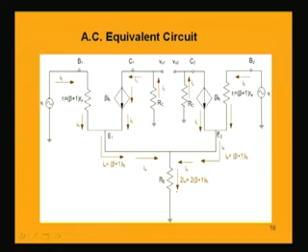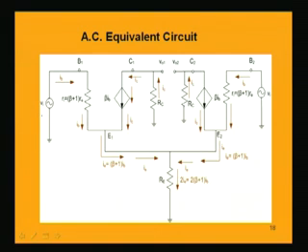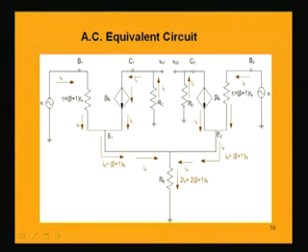Now, what will happen is that you are applying the same voltage to both the transistor input. So, Vi is input to the transistor Q1 as well as transistor Q2. That means the base current which will be flowing in the transistor Q1 and the base current which will be flowing in the transistor Q2 are same, because the transistors are perfectly matched, having same beta value, same input source we are applying, so same base current is flowing. The resistance Ri between emitter and base, that is Ri equal to beta plus 1 Re, is also same in both the cases. Rc is connected in the collector of both the transistors, we are having the same Rc.